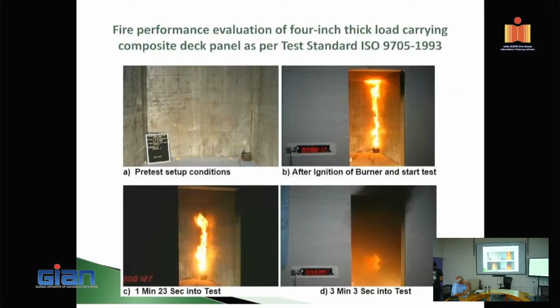This is a corner test, I told you, E119 type test. And again, we tested real fire, 10 feet by 10 feet by 10 feet, and it has to survive a minimum of 3 minutes. A minimum. And we have to worry about smoke, toxicity, and those kinds of things. As the fire goes on, these are the chemicals released. We want to make sure that they are within the parameters that do not create carcinogenic effect.